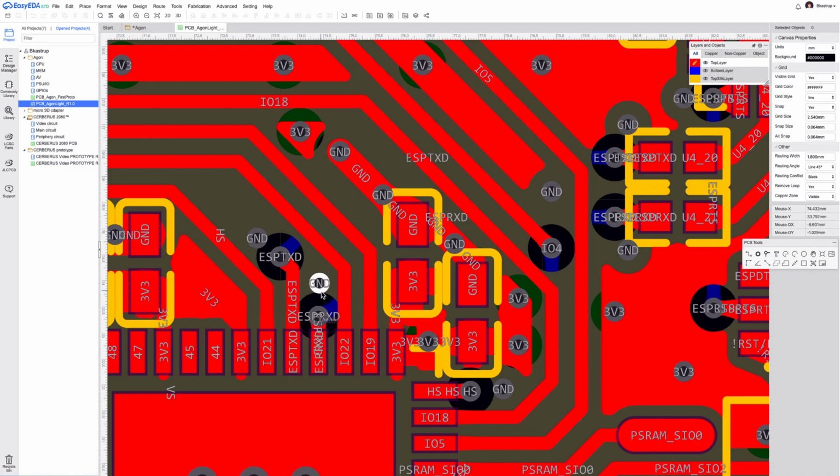So to make sure that the return path is the one you decide and it doesn't spread and doesn't interfere with anything else, you put ground vias next to every signal via, if you can. Often that's not practical, but in this case I could do it. So Agon Light always has a return path ground via next, very close to every signal via.